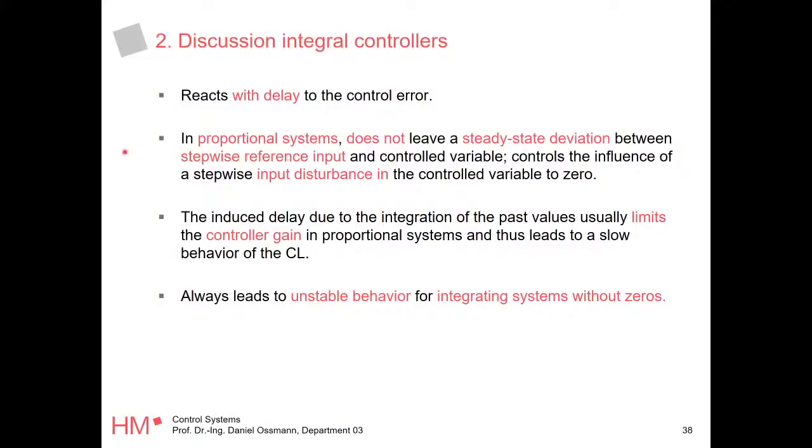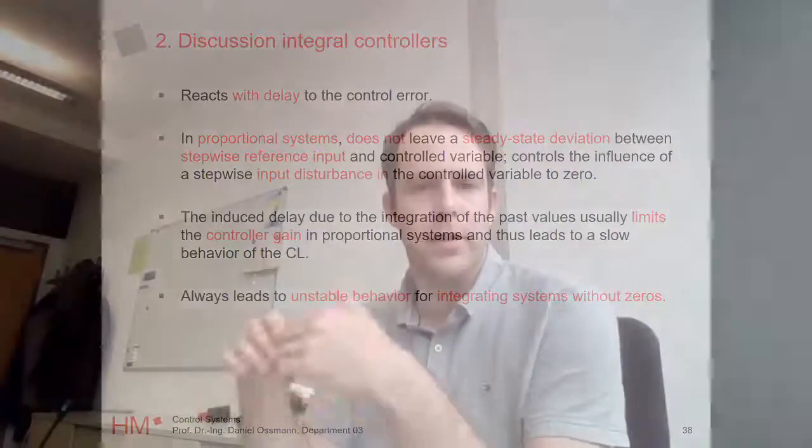So we covered now two of the three elements, right? We said PID controller, proportional gain, proportional element, integrating element. We know what this one is doing. And now we have the differentiating element, and actually you basically never use the differentiating element alone. So you will never hear, oh, I'm implementing a differential controller. This is really, really rare. We mostly talk about proportional controller, integrating controller, or combinations.